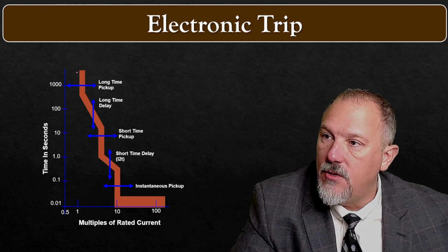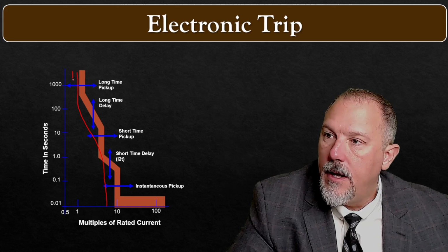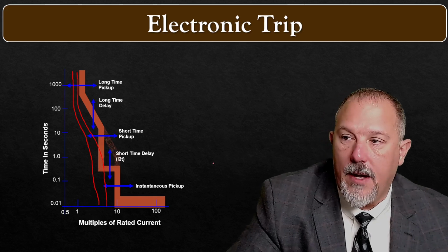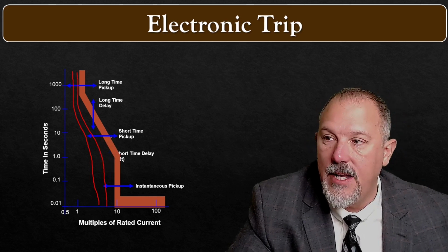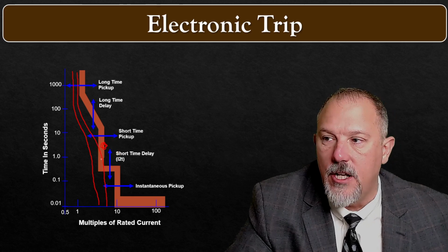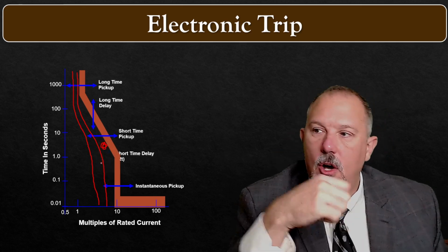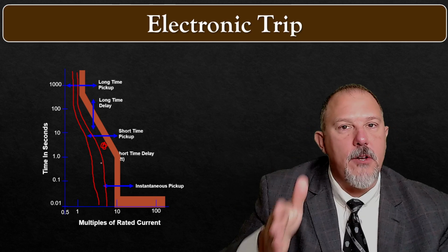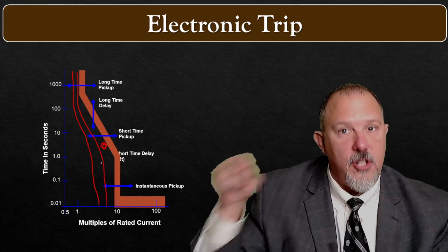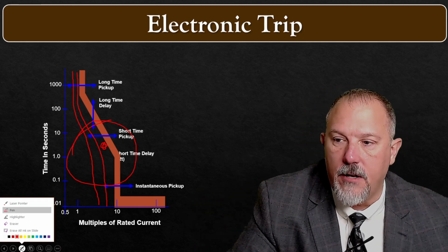Let's say that I have a fuse curve that comes down like this. And I have a lack of selective coordination. What might I be able to do? I can do that, or I can turn it off and say, now I've got clear separation in between these curves in this region. I no longer have a problem. All I did was change a set point on this device to establish a better clearing space to make sure that the fuse downstream goes before the circuit breaker upstream in this region of the time current characteristic curve.